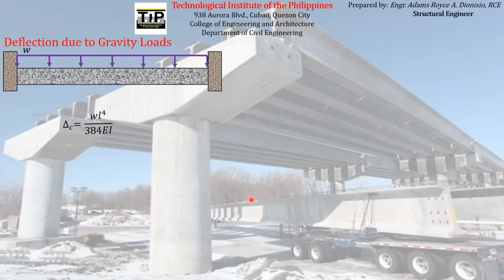And then additional formulas are shown here. For the case of a beam fully restrained at both ends and supporting a uniformly distributed load W, the maximum deflection, which actually occurs again at midspan, is equal to this formula, WL to the fourth over 384 EI.